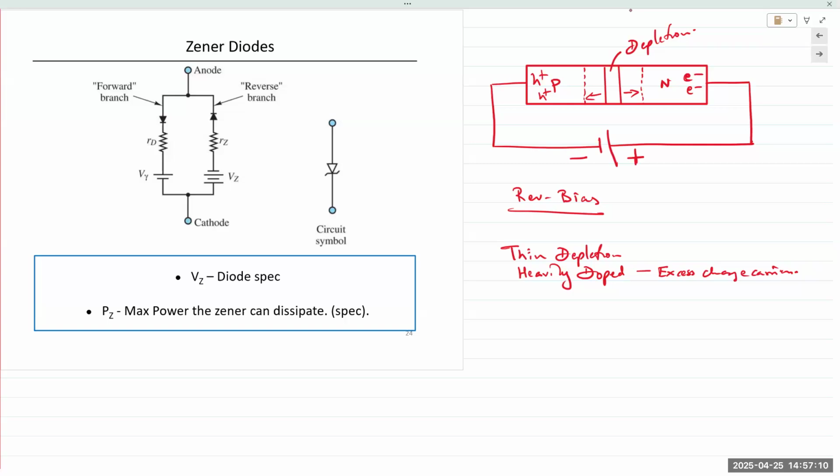In normal diodes, when you apply an electric field, because of the small size of the device itself, the electric field density is quite large, and this is imposed on the atoms that are part of the lattice structure. When this keeps on increasing, after a certain point, the electrons in those regions will acquire enough energy to break free of their bonds and become free to conduct.